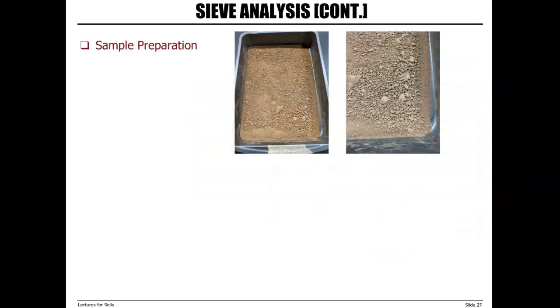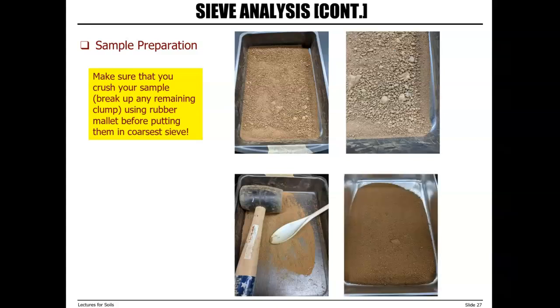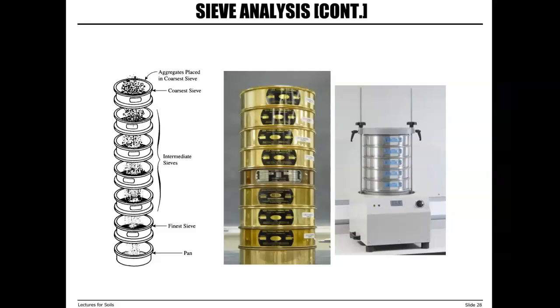Then we need to prepare our soil sample. You need to make sure that you crush your sample using a mallet, rubber mallet, before starting your test. So you prepare your soil sample, use a rubber mallet to break all the soil that are sticking together into individual particles. And then when you have your sample ready, you can start the test.